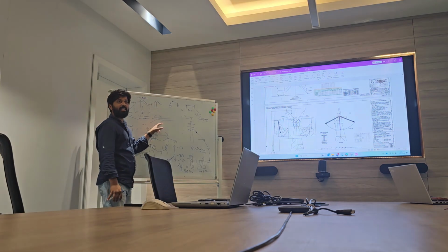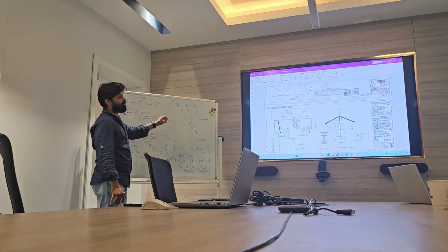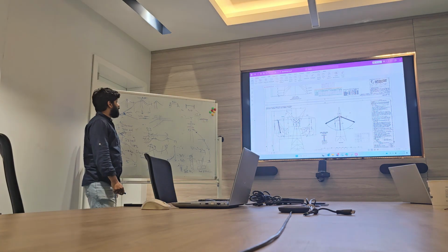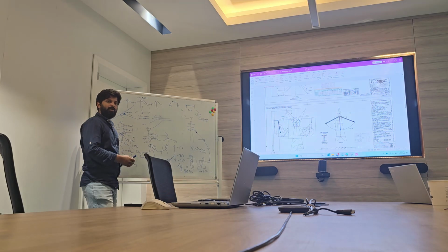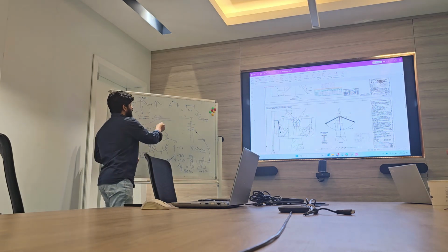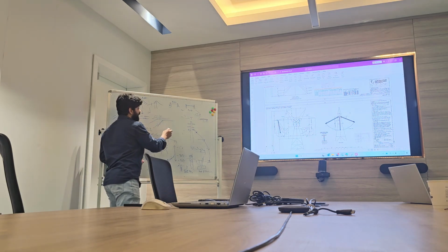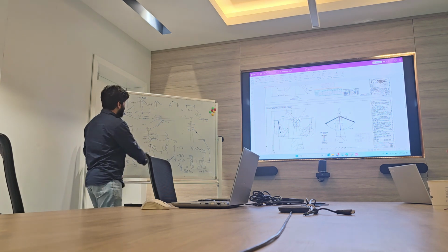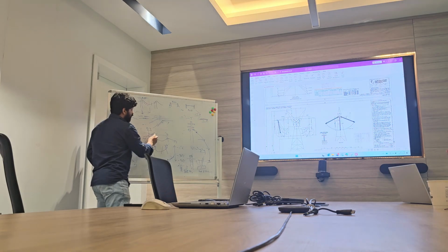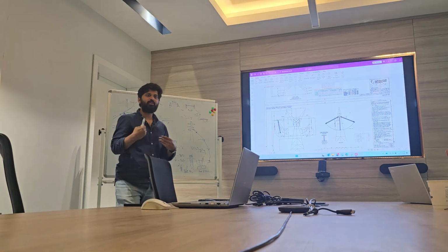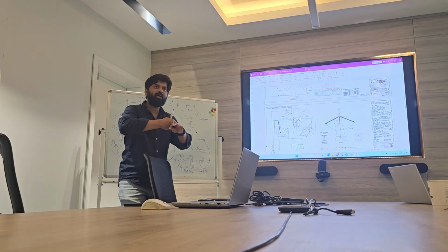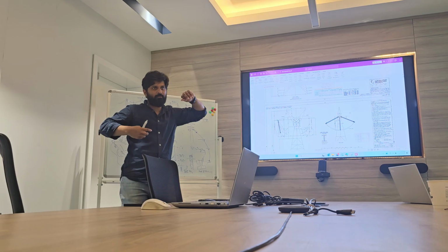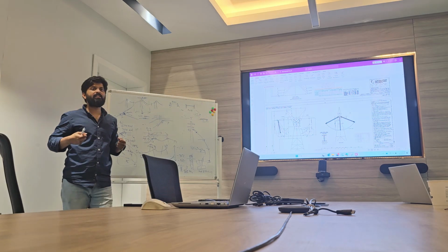Then we were talking about line angle and some other points related to it. A tension tower is a tower in which we put some tension. So in this tower I have some load on this side and some load on this side. In a suspension tower I have only vertical load and only some load on the transverse face, not on the longitudinal face. Longitudinal load will come only under two conditions. One, when the wire is cut, it will try to pull the tower. Another, when you are pulling the conductor itself, or stringing the conductor.